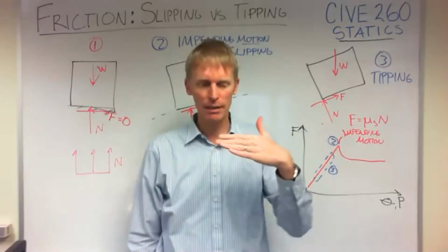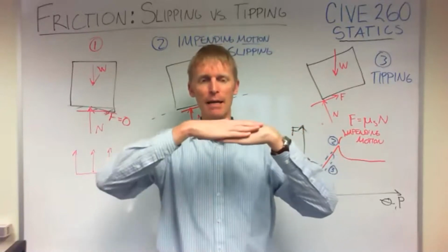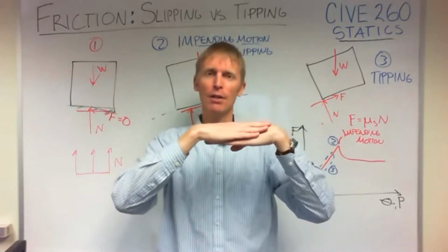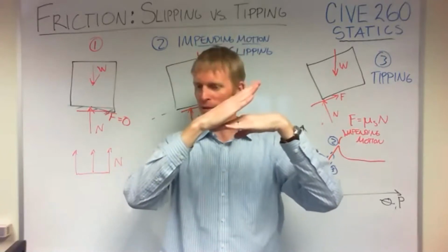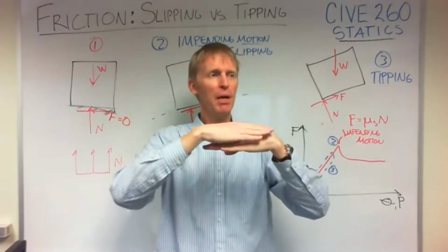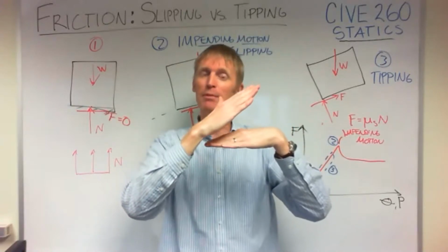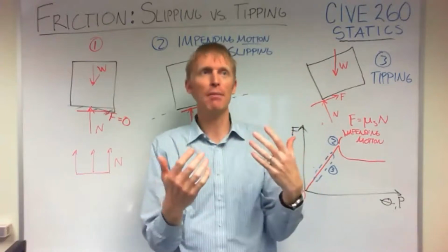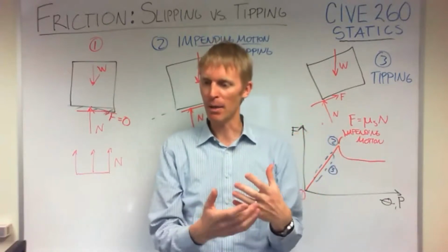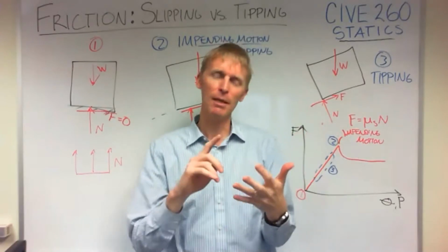One of those, and the simplest one, is you could think, say you're building a parking garage, right? And you want to make sure that cars aren't going to spin out just driving up in that parking garage. So the pitch that you put the ramps would need to be limited fundamentally by whatever you think the worst surface condition that ramp might see. Maybe rain, maybe ice, maybe whatever else.